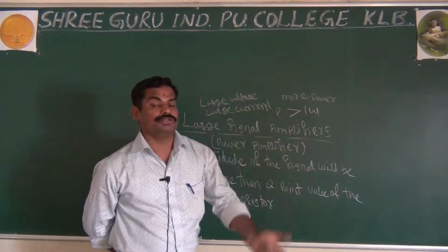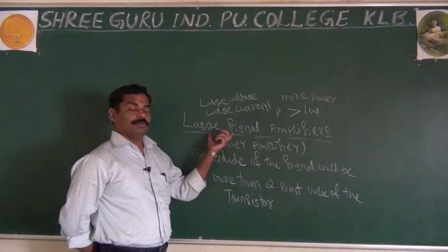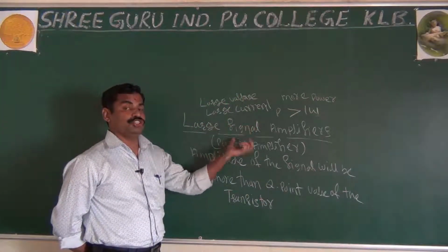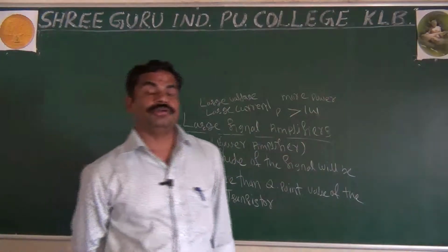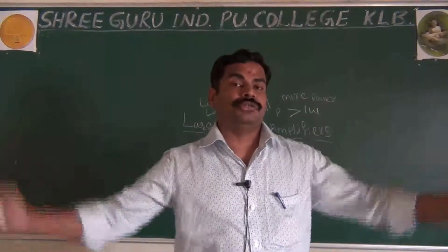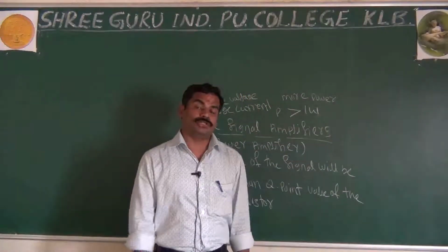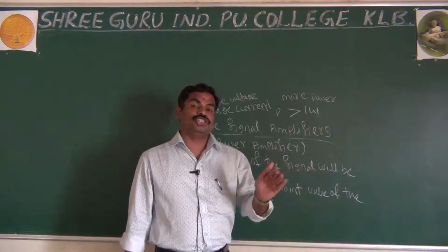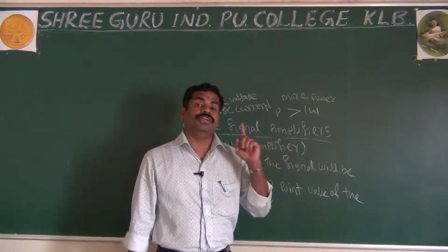Another important thing about the large signal amplifier is that we use it in the last stage of the amplifier. As I said, where we use the small signal amplifiers and where we use the large signal amplifiers: in your radio transmitter or receiver, in the initial stages you use the small signal amplifier because of the voltage amplification.